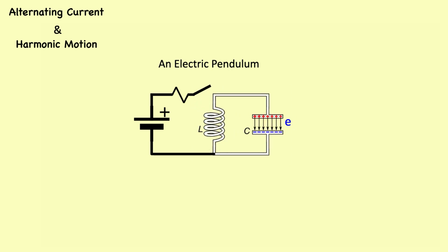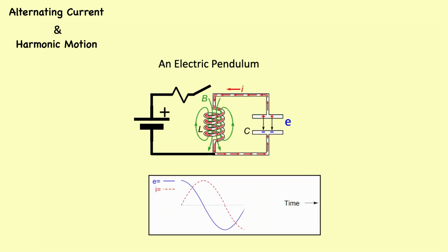The current from the source immediately stops and the current through the inductor will then be zero. The capacitor, then being at the source voltage, will start to discharge through the inductor. The voltage continues to drop while the current continues to rise.